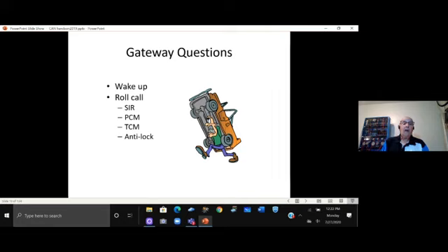Scenario number 1, SIR, when called, answers, I am here and I have no DTCs. PCM does the same, TCM does the same. So you stand there and I say, okay, I'm the gateway. And I can call myself whatever I want, but I'm the gateway. And the first thing I need to do when I see a wake-up signal is I need to call the roll. So, SIR, are you here? And have the student or the technician stand up and read the card. And I do that for 3 scenarios.